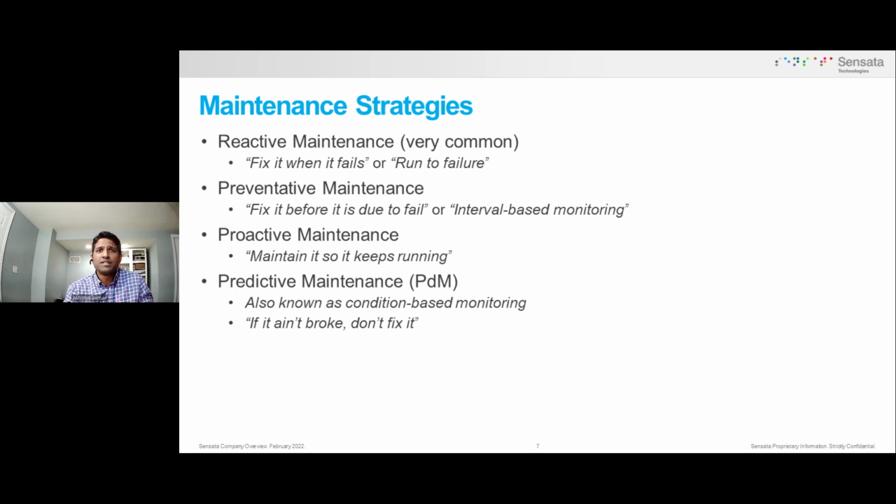So when do you use the predictive maintenance strategy? When it is possible to determine the asset's condition using some technology. It is more cost-effective to monitor the asset and plan repairs than to allow it to fail or overhaul it on the next scheduled basis. The advantage of predictive maintenance is to reduce the downtime and repair costs, avoid secondary damages, and also avoid the cost of keeping spares, which increases inventory costs. The disadvantage is that it takes an investment in instrumentation and training. It may also require additional staff if your current staff cannot be redeployed, requiring a change in mindset.